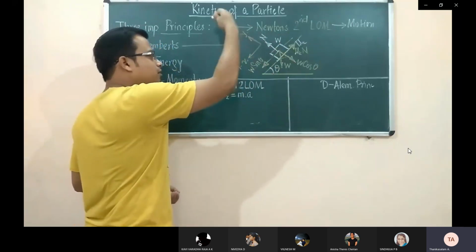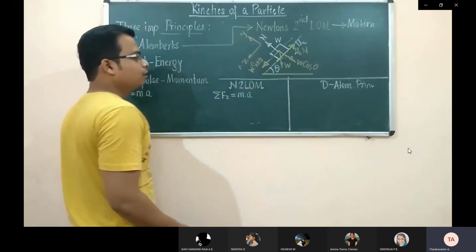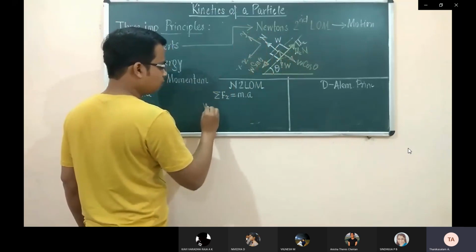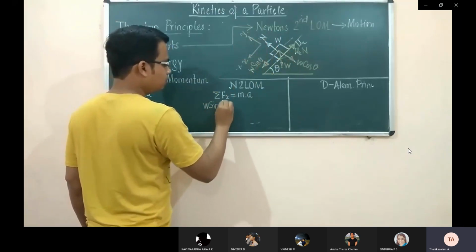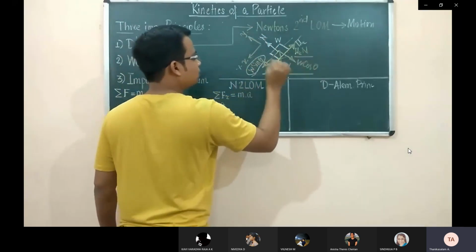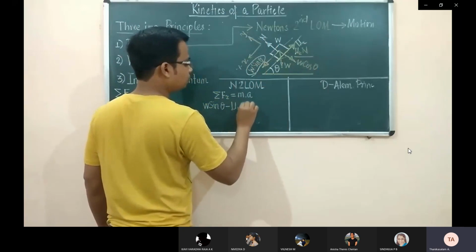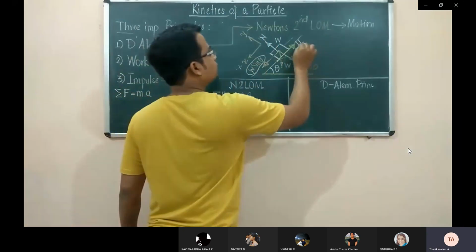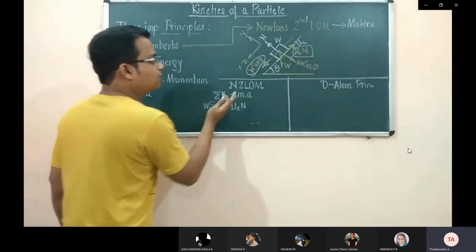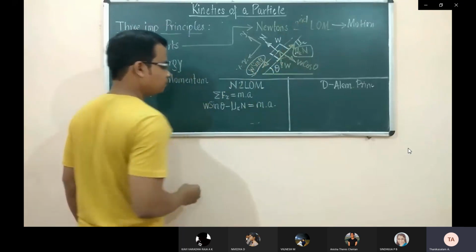As far as the y-axis is concerned, there is no motion, and here the summation of forces is going to be equal to 0. Okay, so W sine theta, since this direction is positive, so we have this W sine theta. What else? We've got this mu k n. We have used this, so I'm going to write it as minus mu k n. These are the two forces acting along this direction, and both of them will be equal to mass into acceleration.